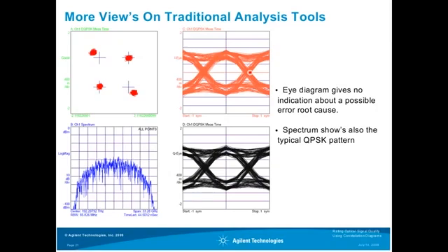This bit stream we can filter, and then we can get a kind of reference trace represented here as this eye diagram display. And from this trace, again, we can reconstruct our I and Q signals, leading to an in-phase reference signal and a quadrature reference signal.